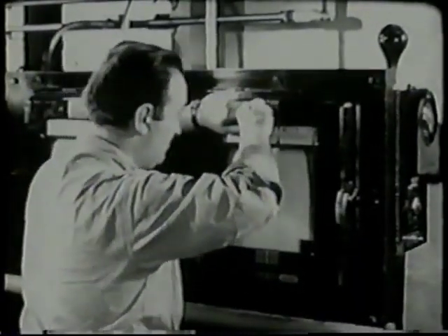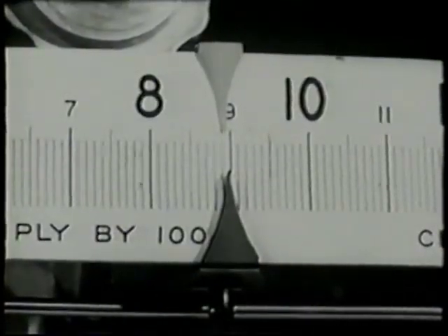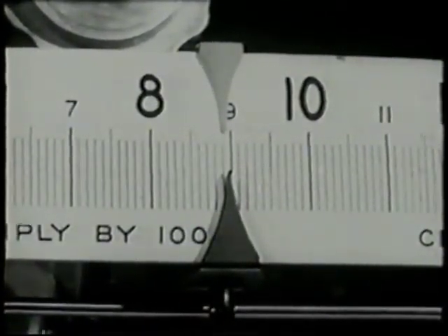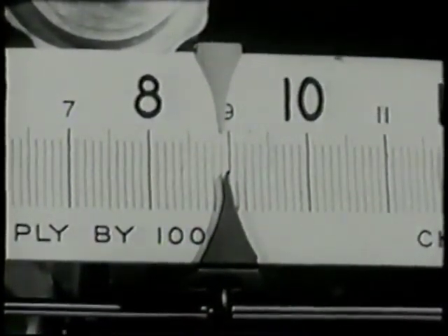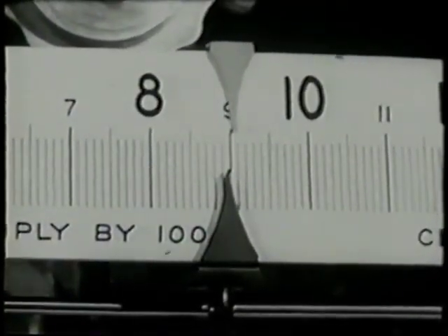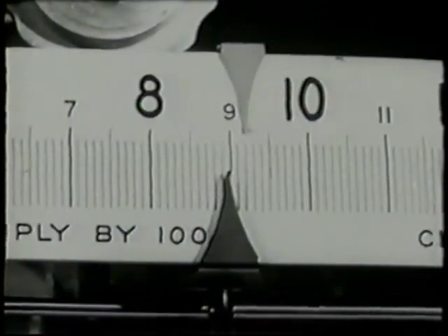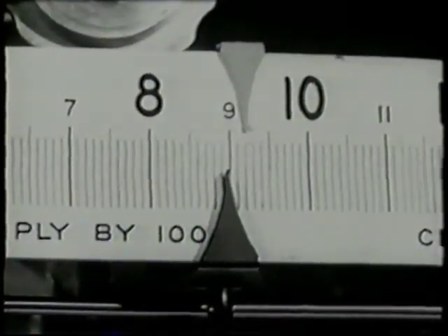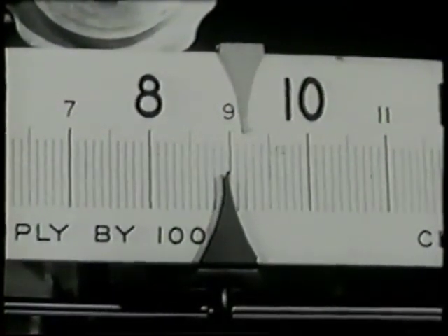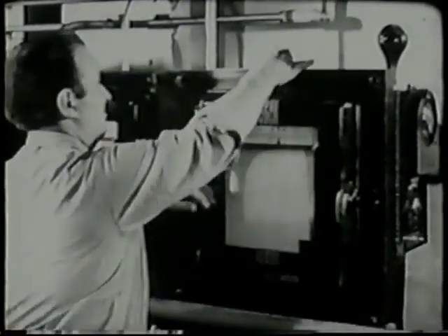Operation of the furnace is guided by automatic temperature and time controls. A thermocouple unit keeps the temperature within the range prescribed for a given alloy. The proper heat treating range for aluminum alloy 24S lies between 910 and 930 degrees Fahrenheit.